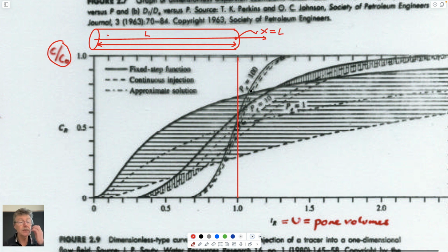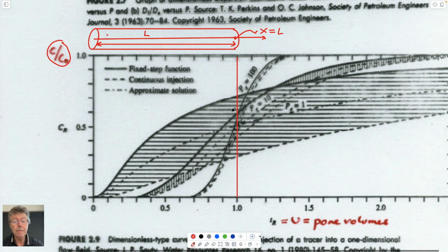And this is the relative concentration, how it builds over time. And what you see, importantly, is that if the Peclet number was equal to infinity, then this curve would look like this. So this is Peclet number equal infinity. And so that's our classic plug flow system. It's moving, there's no dispersion ahead of it, and so it's just moving as a sweep, and the water behind it is holding stuff at equal concentration.